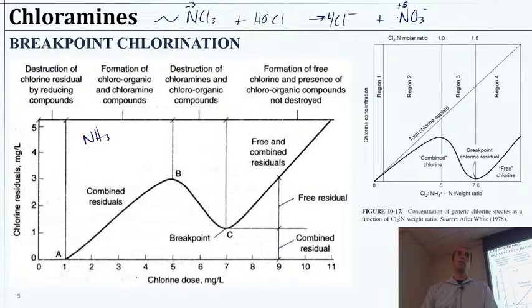Okay, so if we're oxidizing our ammonia from a -3 to a +5, it's going to take a lot of electrons, and chlorine is going to be the vehicle to do so. And it would be destroying that trichloramine. Okay, that's what's happening from B to C. And at some point, we've gotten rid of most of the chloramines. There's probably still going to be some in equilibrium because they just weren't all sent over to trichloramine and reacted. There's probably going to be some limitations there. And then that is what we call our break point.